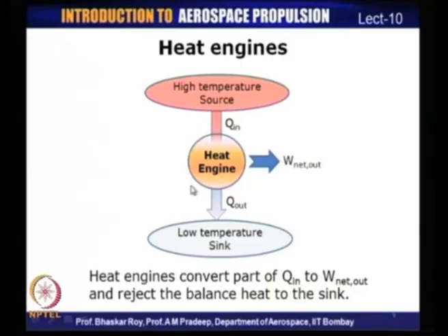It could consist of a pump, a turbine, a condenser and a boiler. All these put together constitute a steam turbine unit which generates a net work output. So it is not just the turbine which constitutes the heat engine, though that is one of the components of the cycle. There are other components, like a condenser. The turbine outlet goes into a condenser, then the condenser outlet goes into a pump, which then goes into a boiler which generates steam.